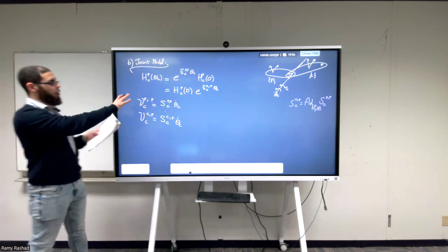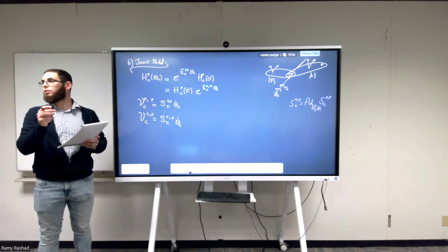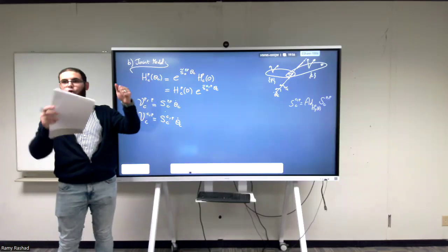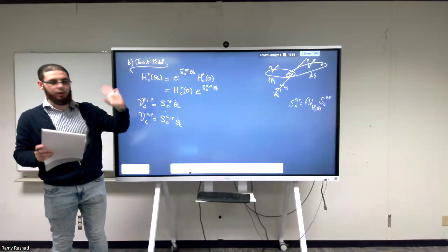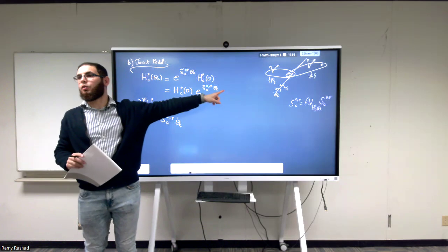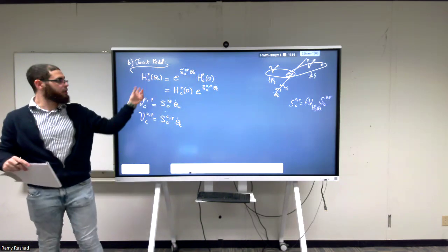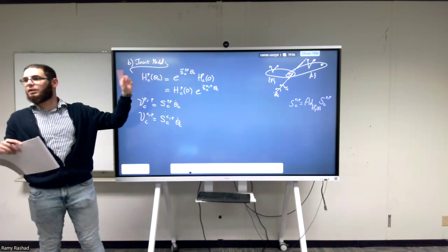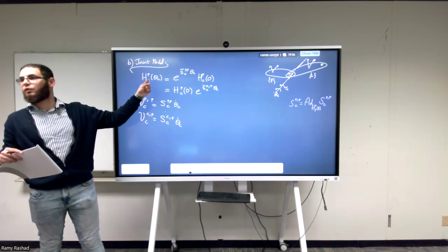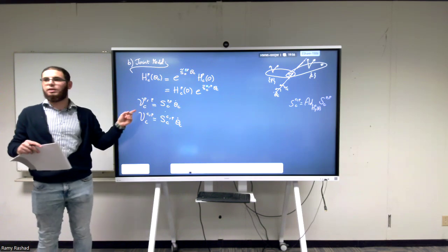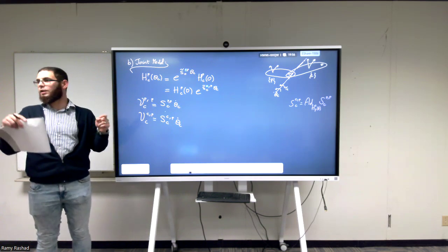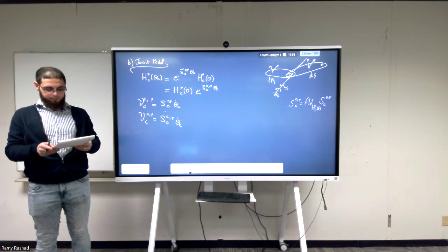So this is all of the information that you have on the joint. Okay, so the joint is only defined by one thing, which is the screw axis, right? And then everything just follows. The relative pose between the two bodies that are connected through this joint follows from this equation, and the relative twist between the two bodies connected by this joint follows from this equation.